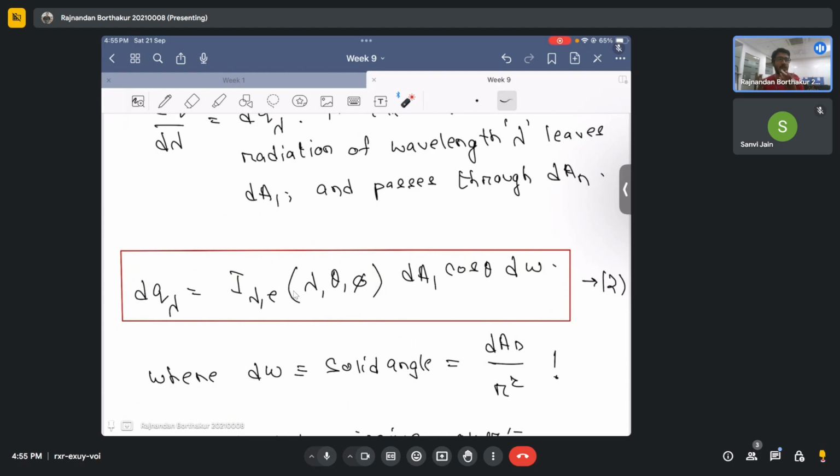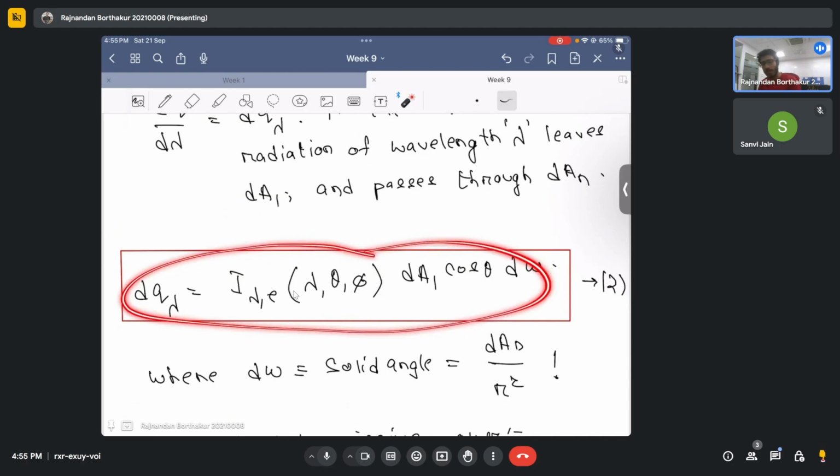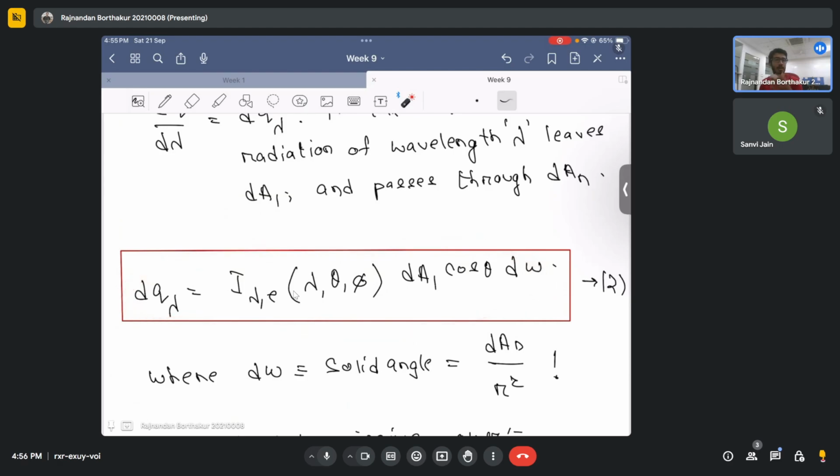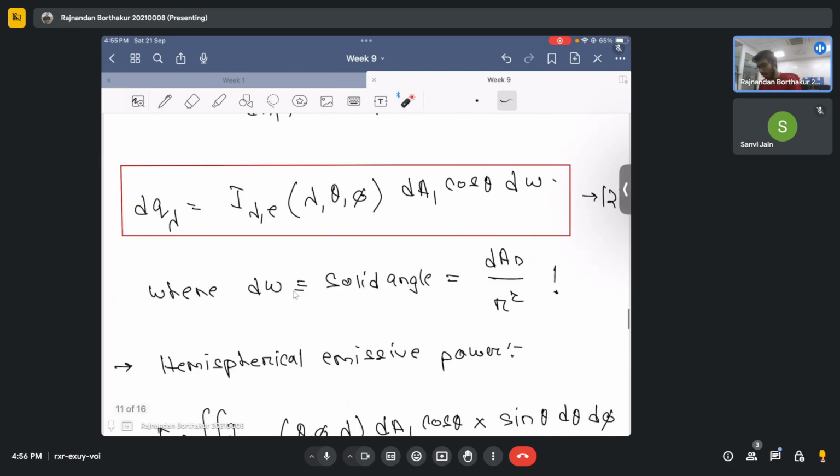This is the basic foundation of deriving something known as the radiation view factor. If you see the derivation, this is where people start and try to come out with the expression of the view factor. View factor is nothing but this quantity that we calculated, q1 to 2. So this q1 to 2 divided by some total quantity is nothing but the fraction of energy that is emitted by one surface that falls onto the other surface, and this fraction is known as the view factor. And we'll see these things in the next class.